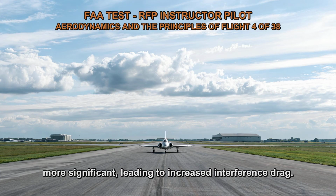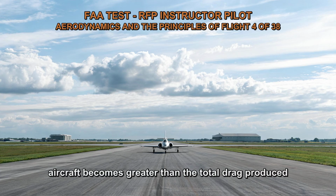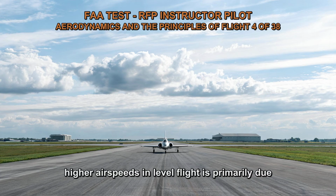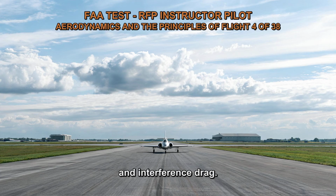increased interference drag. The increase in parasite drag as airspeed increases contributes to a higher total drag. This is why the total drag of an aircraft becomes greater than the total drag produced at the maximum lift/drag speed. In summary, the increase in total drag at higher airspeeds in level flight is primarily due to the increase in parasite drag, which includes components such as form drag, skin friction drags, and interference drag.